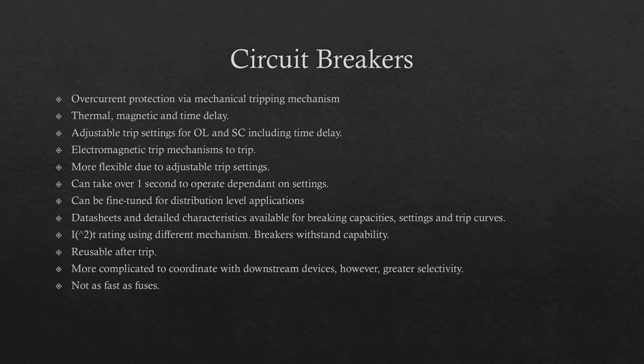Brilliant. The only downside is a circuit breaker will not trip as fast as a fuse. We mentioned earlier 0.02 seconds for a fuse to trip in the best case scenario, depending on the type of fuse and the type of fault. A circuit breaker, depending again on the type and the protection settings, could take up to a second to trip. The calculations for this I'm not showing here, however, it is something to be very mindful of. However, the circuit breaker can be more fine-tuned, which is fantastic about it, and it does lead to it being used more often for discrimination purposes and selectivity.